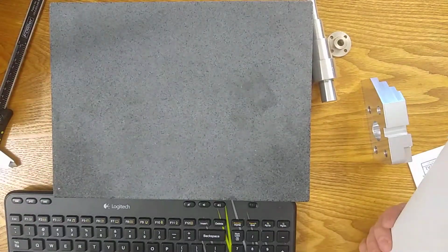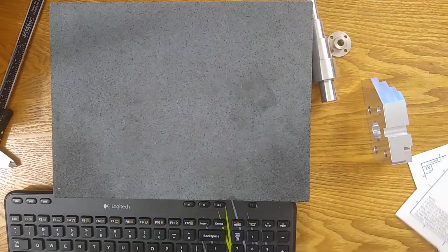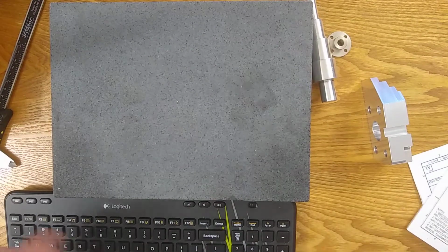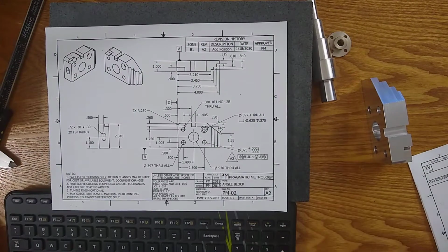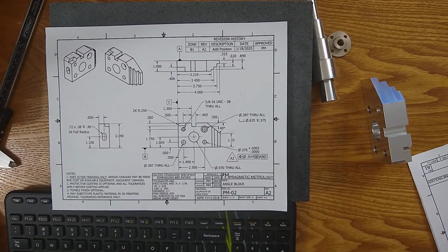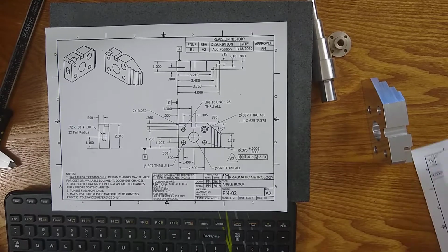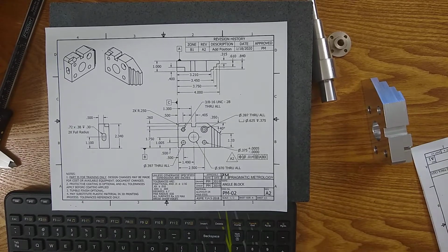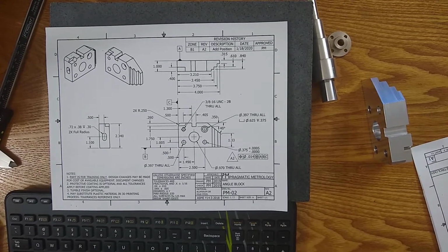So we'll move on. We're going to change subjects entirely. We're going to talk about holes. Now, there's a lot of different ways to call out holes because there's so many different holes. I've tried to show you a cross section of some of the most common that you'll see. On the left there, you've got a through hole, then you have a blind hole, a counterbore, a tapped hole, and a precision hole.